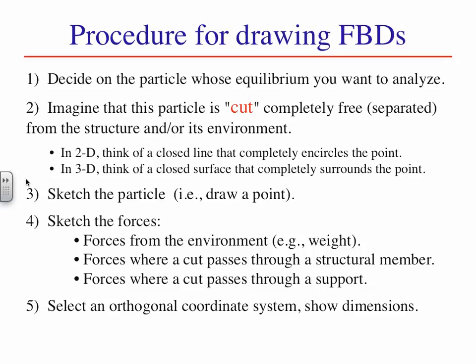Finally, select an orthogonal coordinate system to serve as the basis of the scalar form of the equilibrium equations. You may want to annotate your sketch with angles, rise over run symbols, or other important information to facilitate decomposition of the force vectors into these mutually orthogonal directions. Having done all this, you are now in a position to write equilibrium equations with the free body diagram as a vehicle for writing those equations.